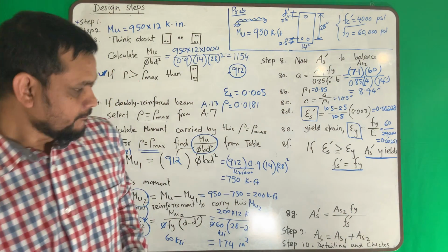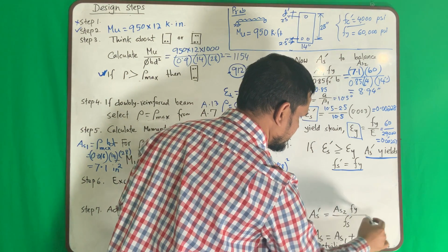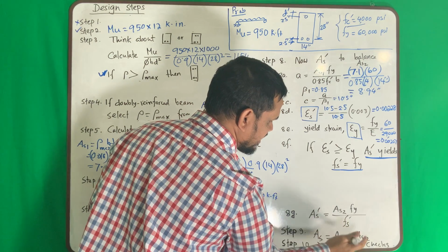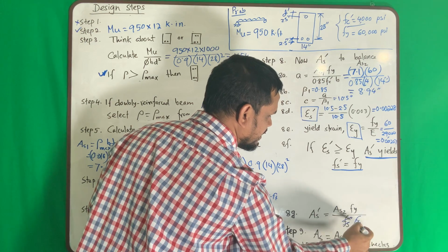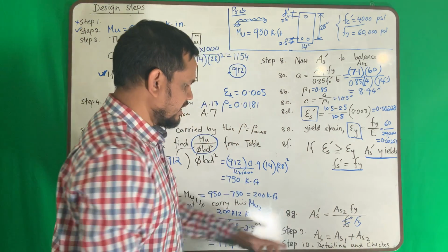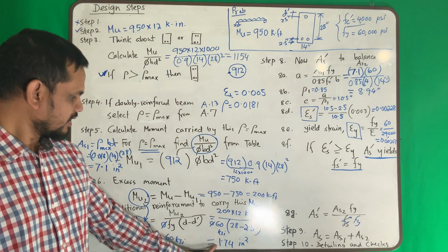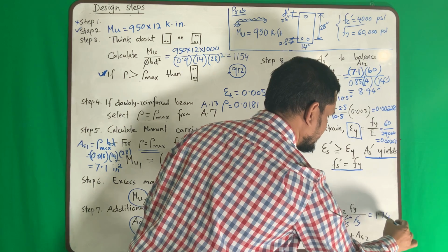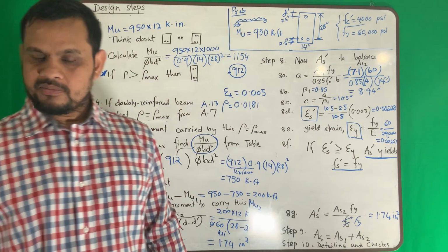Okay. Then what is my reinforcement here? Using this equation. Now, as Fs prime is Fy, I can write here Fy. Delete it, I can write here Fy. Fy cancel. AS prime is AS2. What is AS2? 1.74 inch square. So we solve this problem.